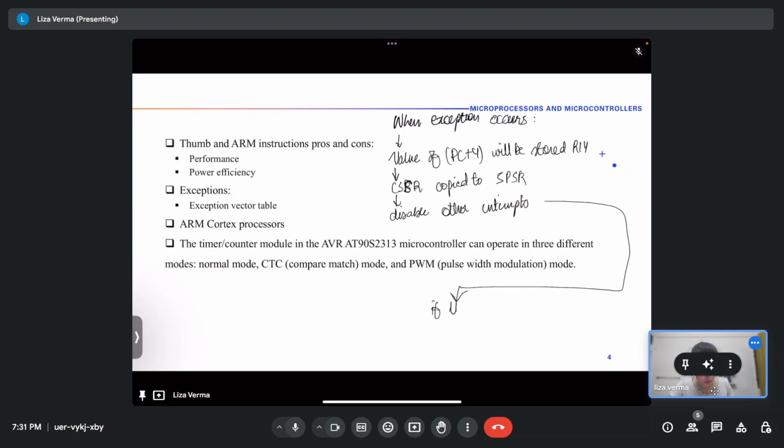If it's not from FIQ, then you would want to be interrupted by FIQ because FIQs are the highest priority, right? But if it is from FIQ, then you want to settle this first. So if the exception was from FIQ, disable FIQ too.